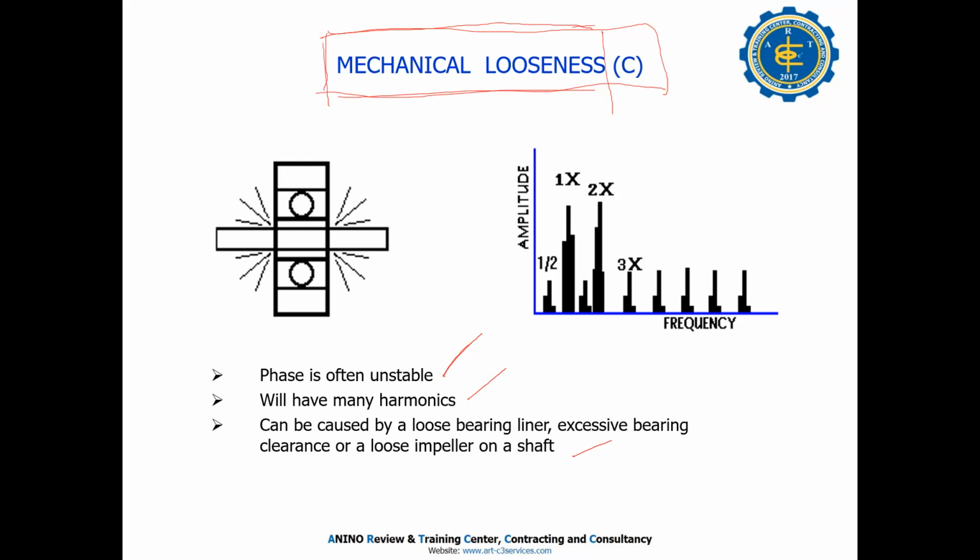The gearbox is very hard to make crack, very hard to damage. In a gearbox, the one that fails first is the bearing. When the gearbox produces abnormal sounds, it is because there is impacting, the bearing is misaligned, or the impact is not good. Yes, it's true.